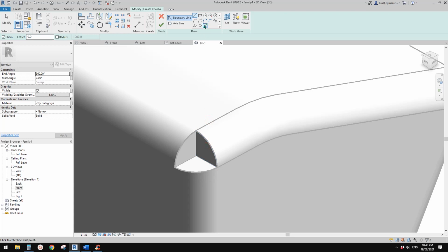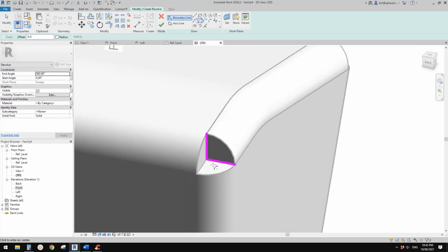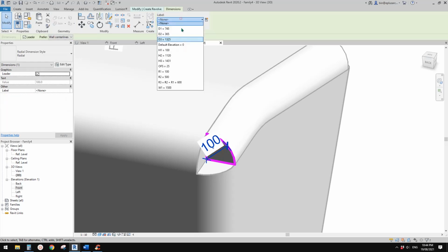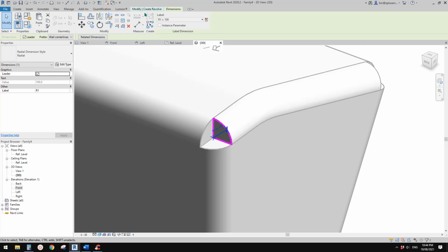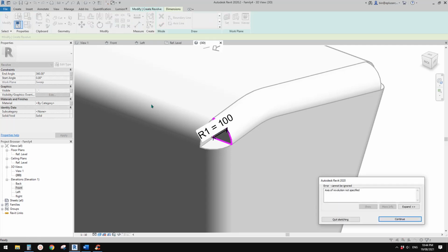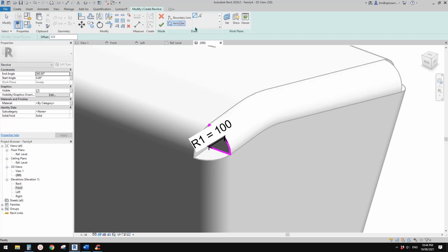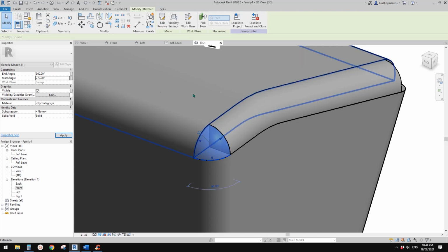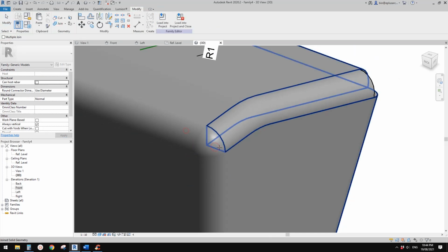And then create revolve, set work plane, pick plane. Okay, pick this plane, pick line 1, 2, trim. Another one will be the arc, and dimension radius. Make sure you pick this edge. Okay, so see, don't pick this face. Pick this edge. So use tab and then link this to R1 and finish. Axis line. Pick this, finish, 270, and let's see if we can join them.